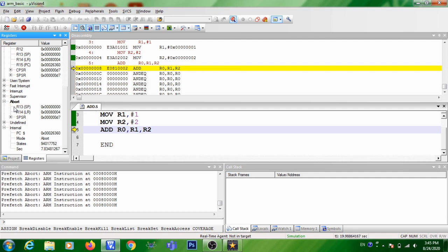By incorporating the short jump. You should not allow the program counter to go to a location where instruction is not there. That means you are telling the program counter to keep on executing a particular line infinitely. That line is known as short jump, right? So we need to modify that.